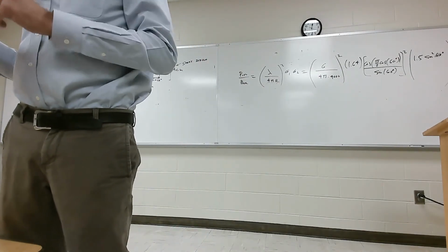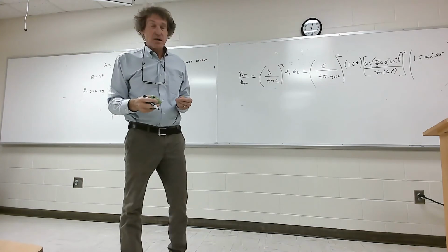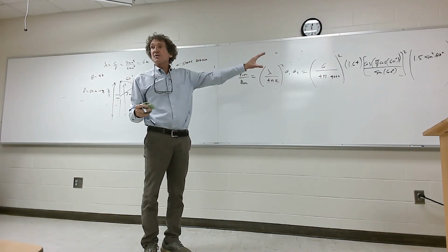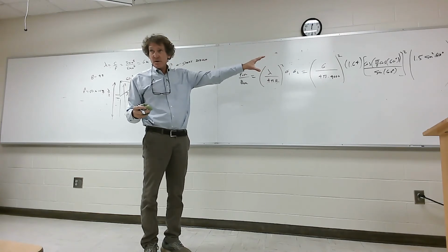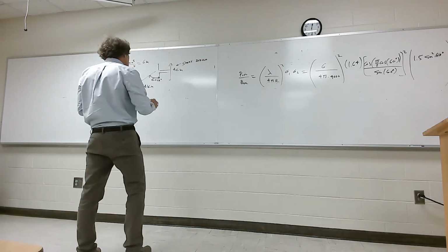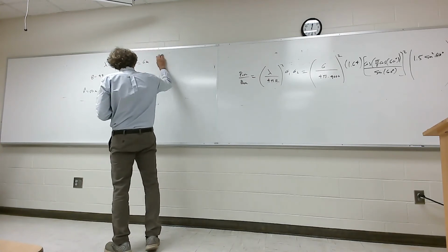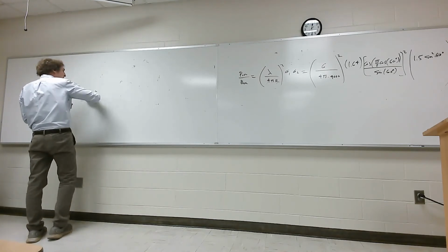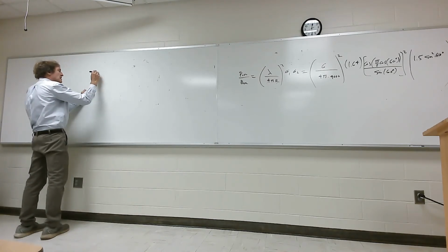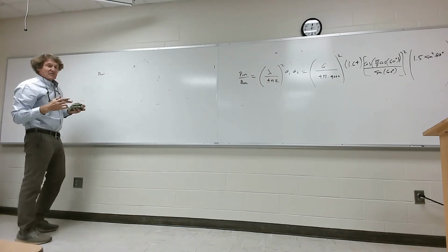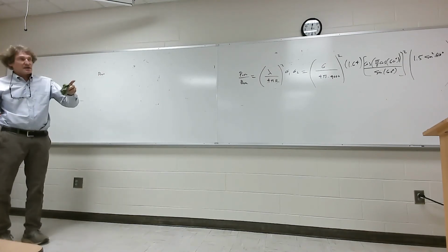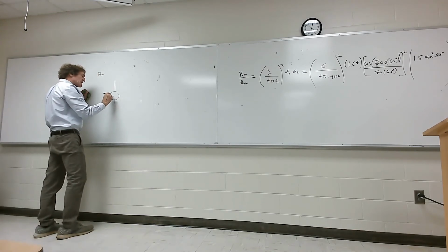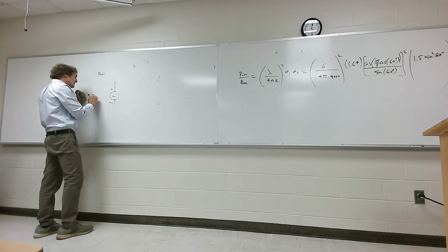Now, if I actually gave you the amount of power transmitted, you could calculate the amount of power received. Y'all follow me? Then you would have to get the open circuit voltage, remember that, in order to complete the problem. I just want to mention this. So, for this problem, if we had a certain power transmitted, you have the ratio, then we could get the power received. But in order to complete the problem, if I attach any kind of load to the second antenna, then you need to find the equivalent circuit here, the plus or minus VOC.